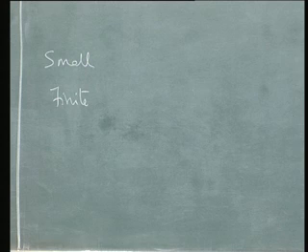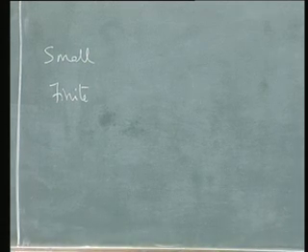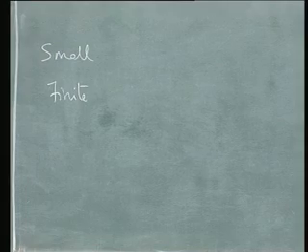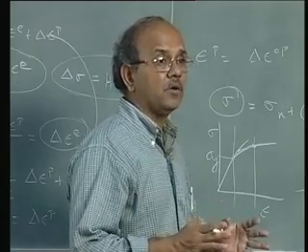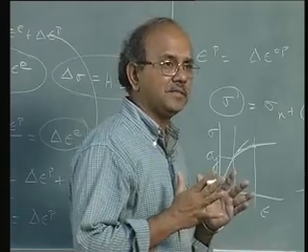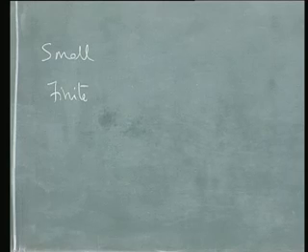So, when I update my positions of the nodes, or in other words, the length differences are important for the definition of the strains and the stresses, we go into finite deformation.